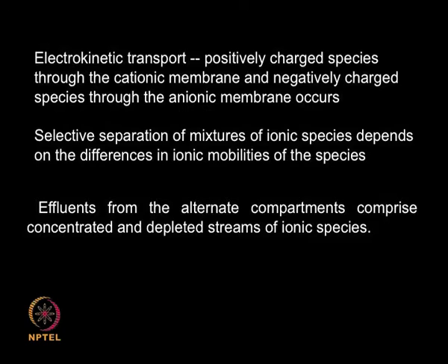So we can use it for selective separation of mixtures of ionic species, depending on the difference in ionic mobilities also. So some smaller ions may be able to diffuse much faster, so they are much more mobile. Larger ions will take much longer time, so we can use it as a function of mobility as well. So the effluents, that means the liquid that is coming out of alternate compartments, will be concentrated in the ionic species and depleted of ionic species. So you will have concentrated, depleted and so on actually. So that is the advantage of this particular setup.